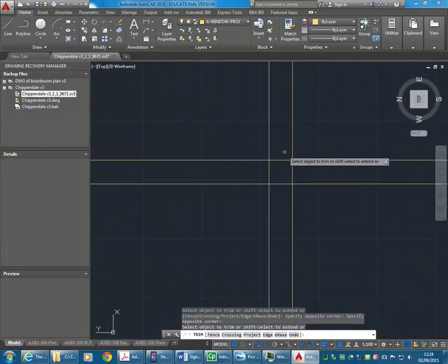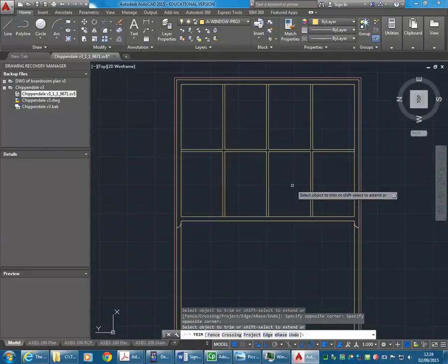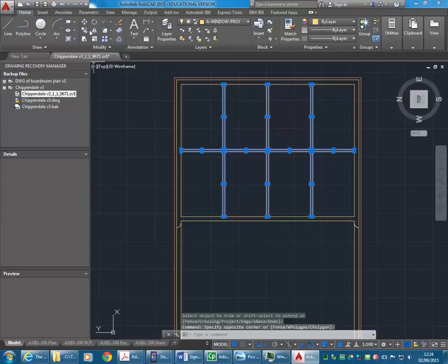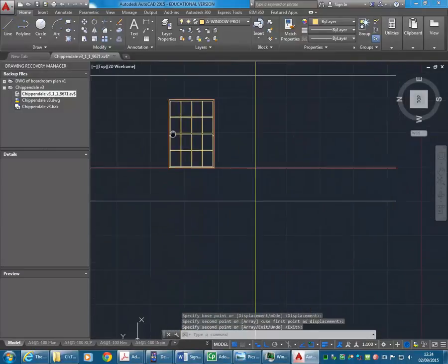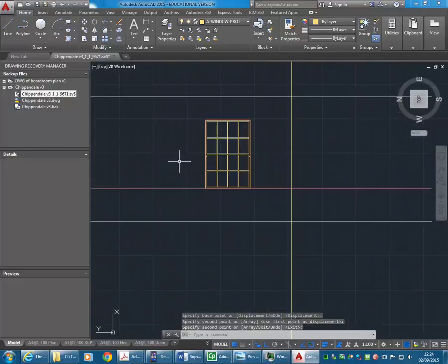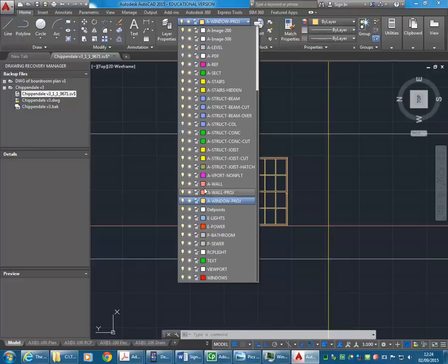And again, it might seem like a lot of work, but all the windows are identical. So do one and you've done them all, except for the ones that have 3 and they're easy to modify. So there we go. And the position of the window openings on the elevation is not critical because you should never take horizontal measurements from an elevation anyway.